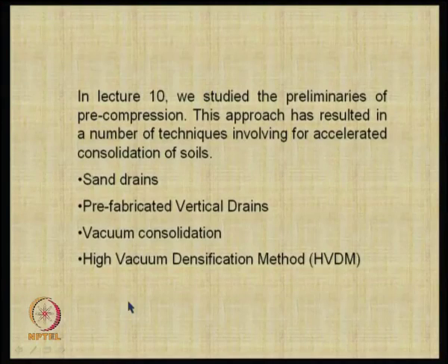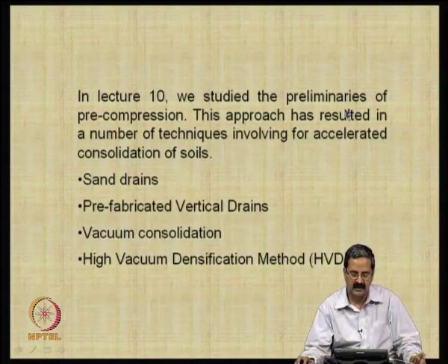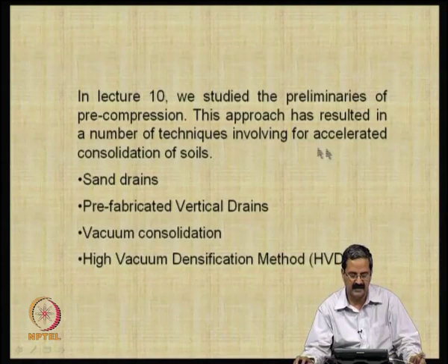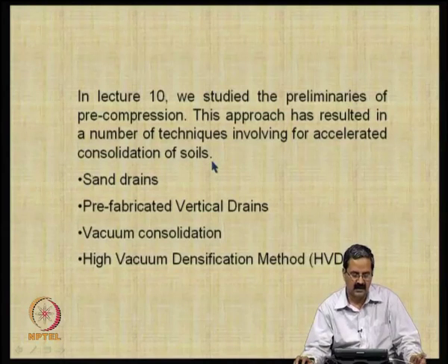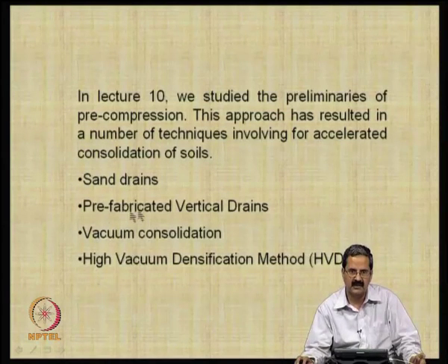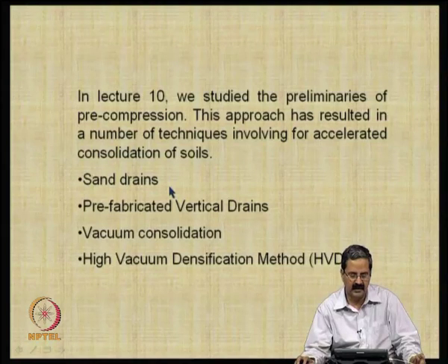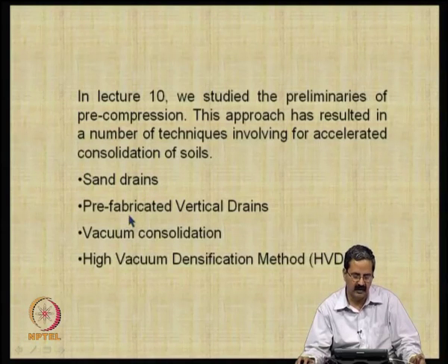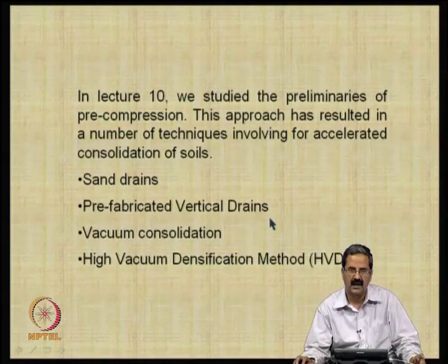So, in the last lecture, that was lecture 10, we studied the preliminaries of pre-compression. This approach has resulted in a number of techniques involving accelerated consolidation of soils. People started with sand drains, and the vertical consolidation as well as radial consolidation was taken advantage of, and subsequently they went to prefabricated vertical drains, because as I just mentioned in the last class, there are some problems associated with the installation of sand drains.